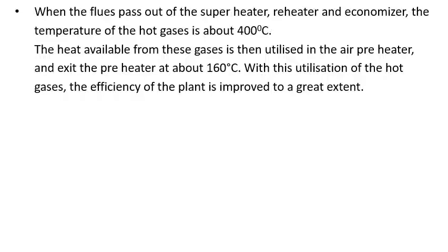The heat available from these gases is utilized for the air preheater and can be brought down to 160 degrees centigrade. That also depends on the sulfur content of the fuel, right? As we discussed in the earlier videos, the dew point and the sulfur content play a very important role in deciding what temperature I have to exit the exhaust gas at, right?